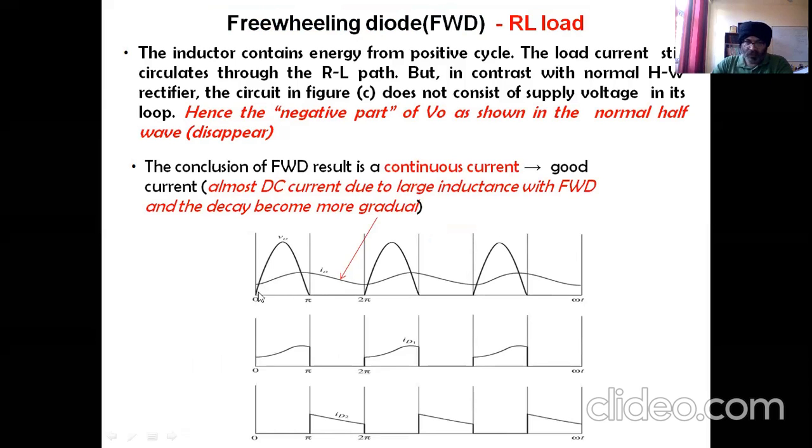What about the current? This is the voltage waveform. It actually resembles the pure resistive voltage waveform as we saw in the very first circuit. So the presence of the inductor will not have any effect on it by clipping the negative voltage supply. Now about the current.